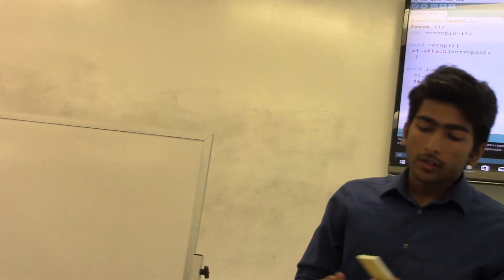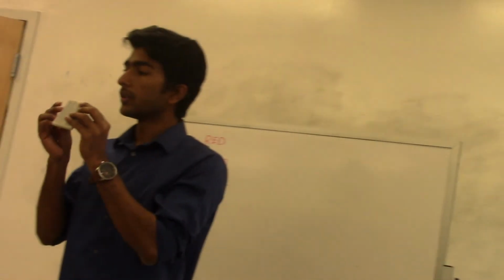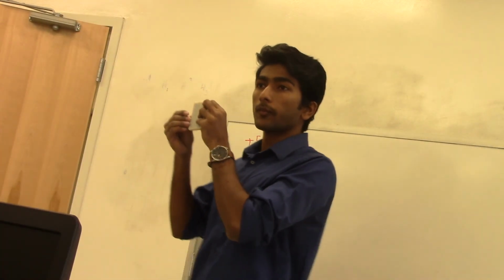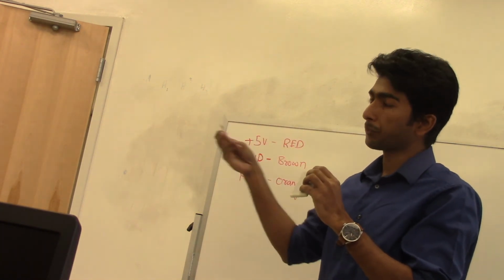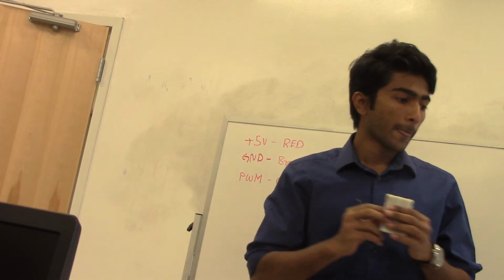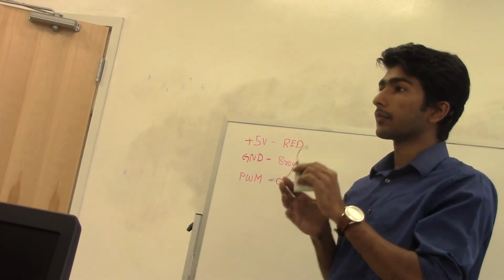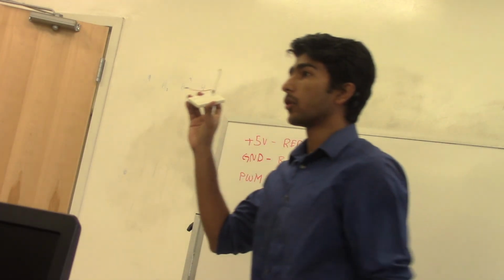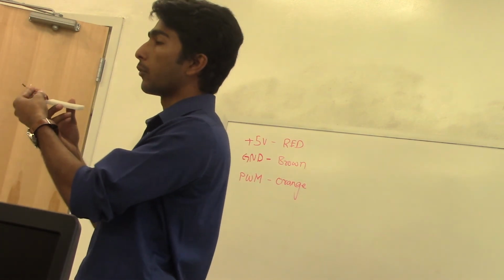So if you want to connect, let's say, 3 servo motors, you need to use 3 5-volt supplies, but unfortunately in Arduino you only have 1 5-volt pin, right? So use that 5-volt pin and connect it to the plus sign set of pins right here. On your Arduino, use the jumper cable, connect the 5 volts, and then where it says negative, connect the ground. So you should have 2 wires going to the power line. Positive and negative should be connected to the Arduino 5 volts and the ground.